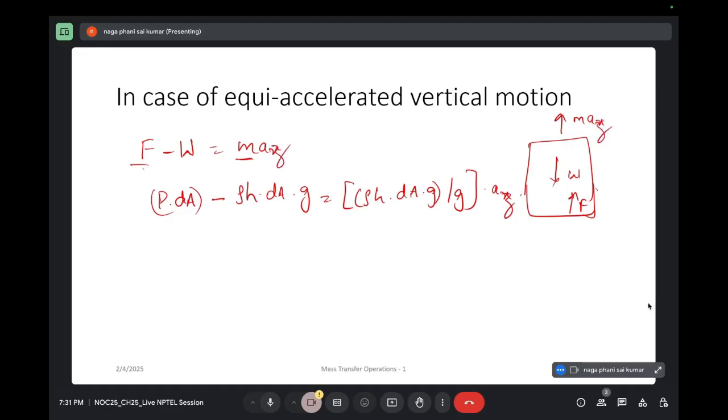Okay, it's moving in upward direction. It will be az. So now for vertically downward direction, or let's simplify this first. Now P will be equal to rho g h plus rho g h az by g. Now if you simplify this, you will get rho g h into 1 plus az by g. Okay, and similarly for